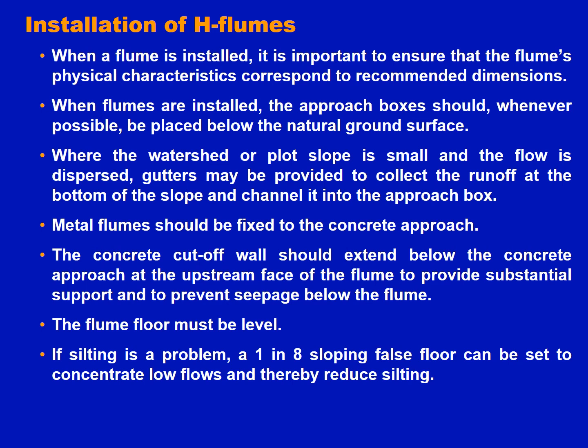That means, suppose we want to measure the discharge in a plot, and we do not get all the water of that plot at a particular point, then we have to install 3, 4, 5, 6, 7 small channels, or gutters, collect the entire water to one point, and then install the H flume, by which we can measure the discharge of the entire plot.